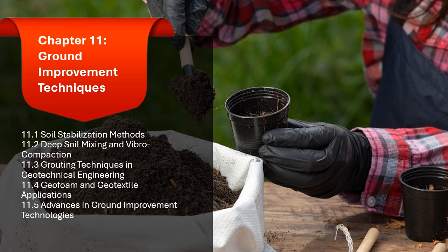3. Vibrocompaction and dynamic compaction. Vibrocompaction involves the use of a vibrator to compact loose sandy soils. The vibration helps to rearrange the soil particles, reducing voids and increasing soil density.